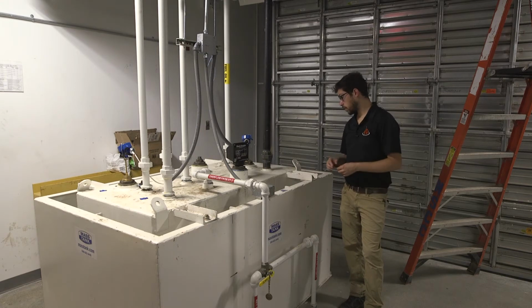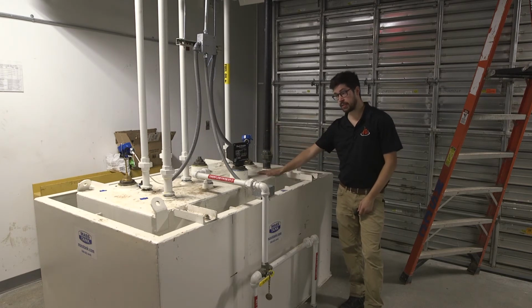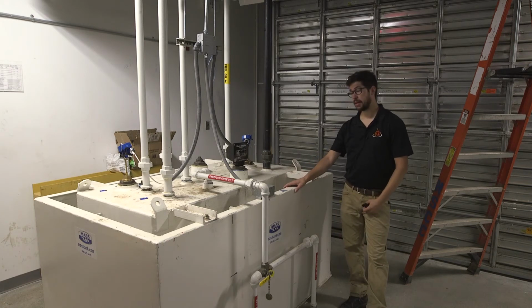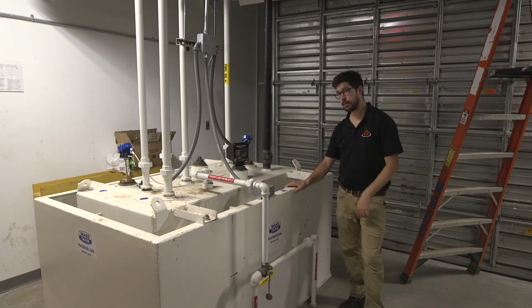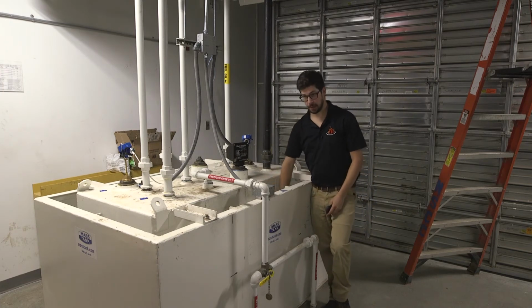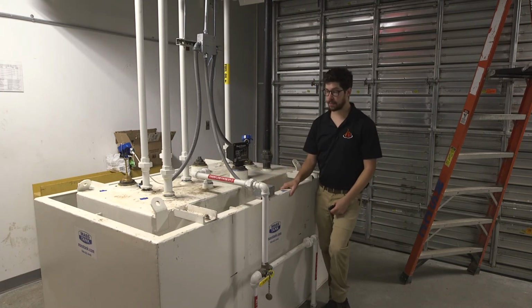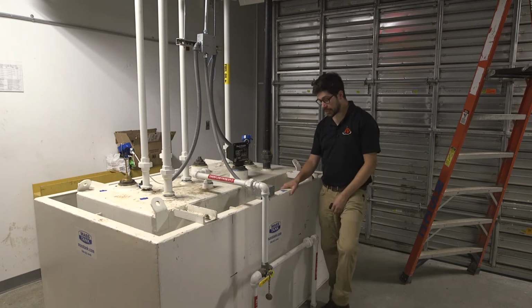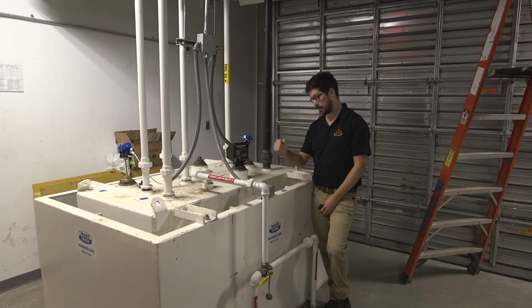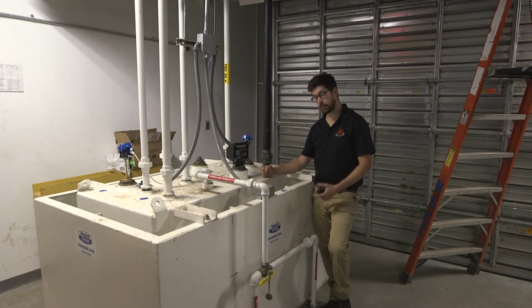So what we have is a single tank with a tank containment around it, much like the other one, with the exception that your other one is completely sealed on the top. You're not able to reach your hand in between the two tanks. This tank is a 200% containment, so the volume of this main tank is 250 gallons to match your old one. In terms of total, 100% capacity is 250.